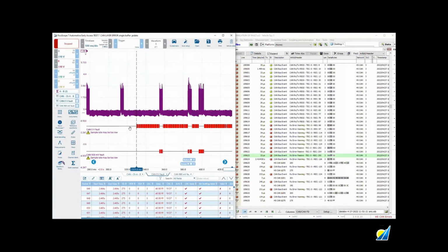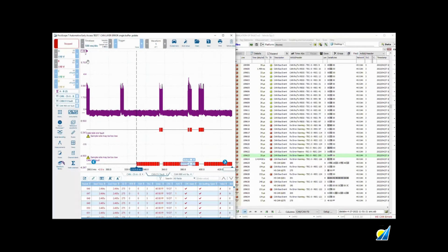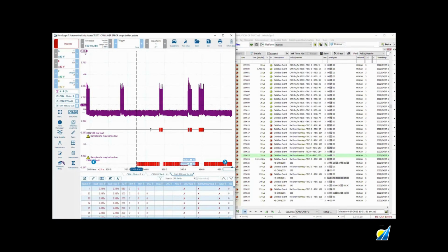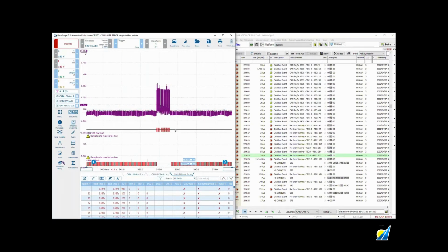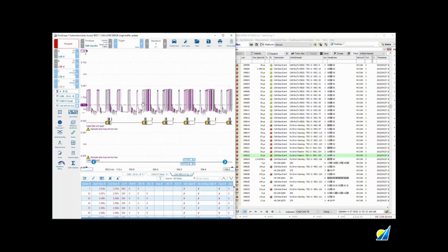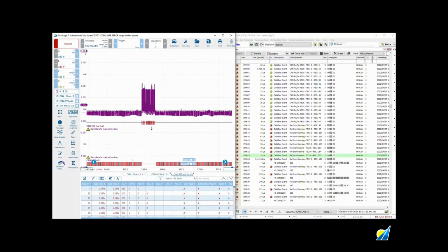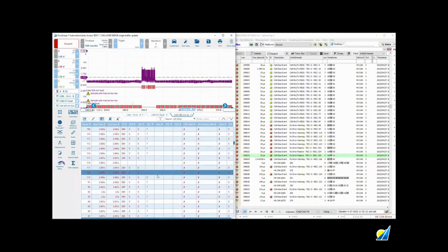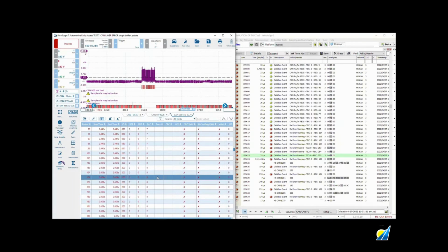Okay, so let's have a look then at this area here. This is the decode at 900 millivolts. So I've chosen a crossing point of approximately 900 millivolts. Let's click on here, and this is suggesting that ID 80 and 200 are attempting to decode during the fault condition. So we've got 80, 200, 80, 200, and I think there was 280 in there as well.